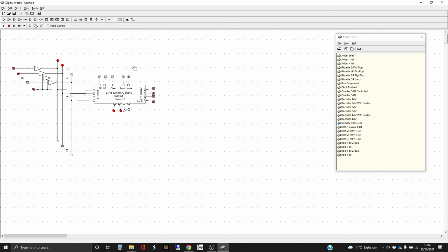Have we checked everything? We've done bus read and output enable over here. We've done the bus connectivity. The values seem to be working. We've used a clear. Let's use another clear just to check that. We've done reading and writing, so let's do a final clear. And that should have cleared all the memory locations. Let's read from 1111, and it is 0.